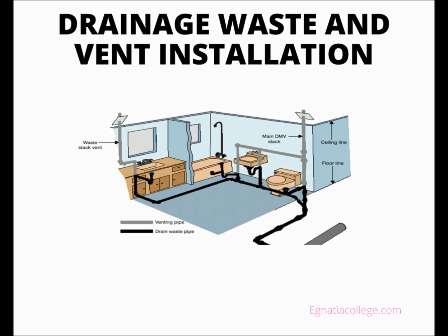A blueprint indicates the fixture locations, but usually not the area of the building that is connected with the building sewer. The building sewer and building drain are connected at the low point of the building drain. When the plumber locates that, the main piping artery of the drainage system can be established. A plumber determines the building drain route based on job site conditions.